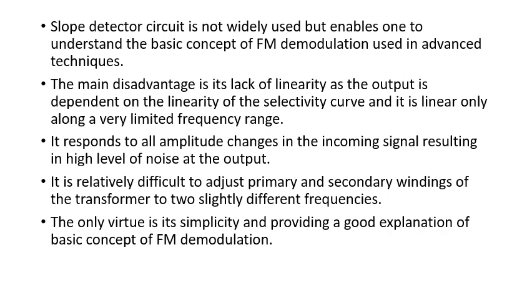As we have mentioned earlier, the main requirement is that there should be a direct connection between the frequency deviation and the output voltage. That is, the output voltage should be in direct proportion with the frequency of the incoming signal, and that condition is satisfied only when the frequency deviation of the FM signal falls on the linear portion of the selectivity curve.